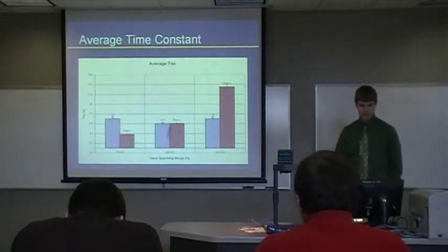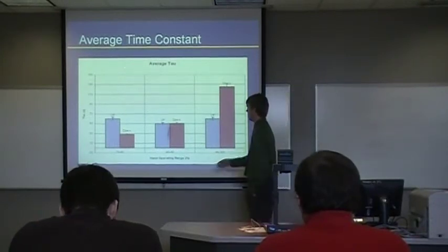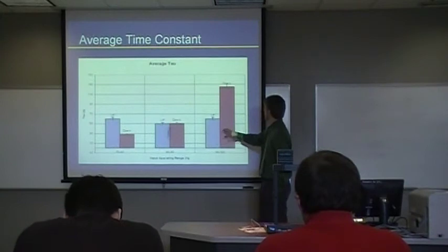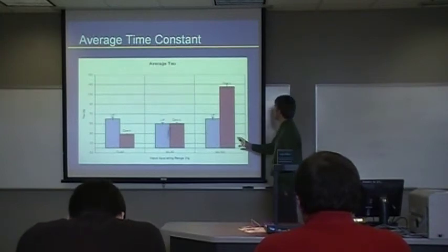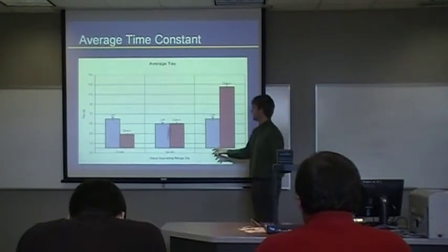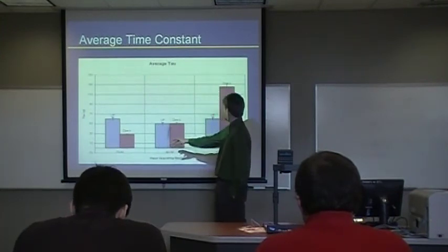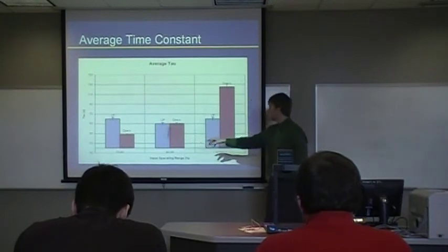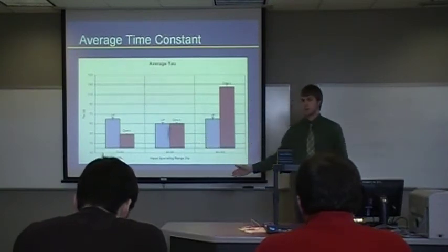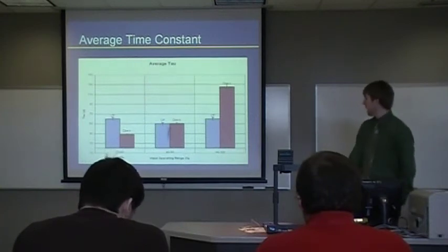Our average time constant was similar to the gain. All of them hung around 50 to 60 seconds, except for 2 major outliers. On the way down, when we ran at 90 to 100%, the time constant to get to 63.2% of delta C was well over 2 minutes, and our 70 to 80 down only took 30 seconds to reach. So it was steady state in theory, but in practice it fluctuated some, as you can see from these graphs.